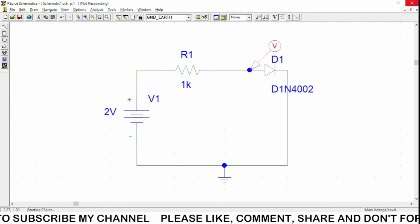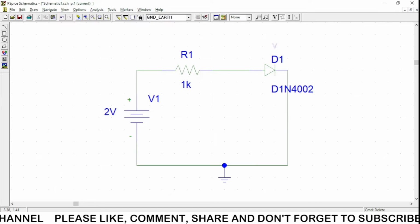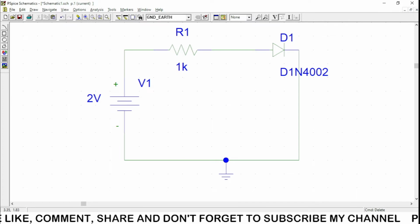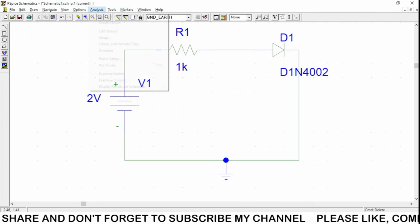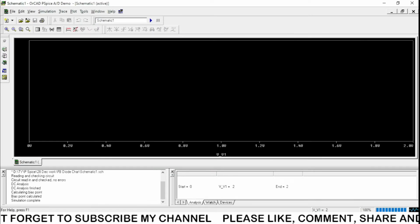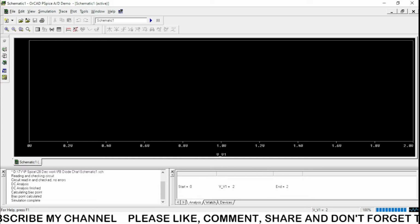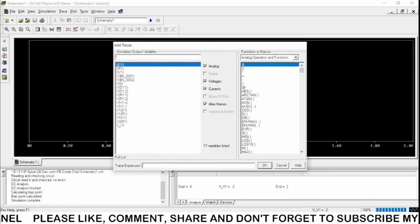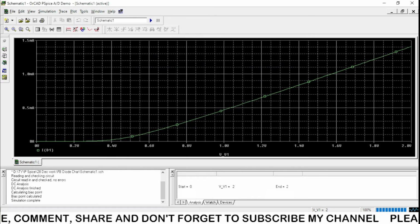We are going to see the simulation window. You can see here. So we are done. Analysis, then simulate. We are going to simulate it. We are having a blank window. Then we are going to add the trace. So trace, add trace, we have to plot the current. I am going to press ID1. Okay, so this will be the current.